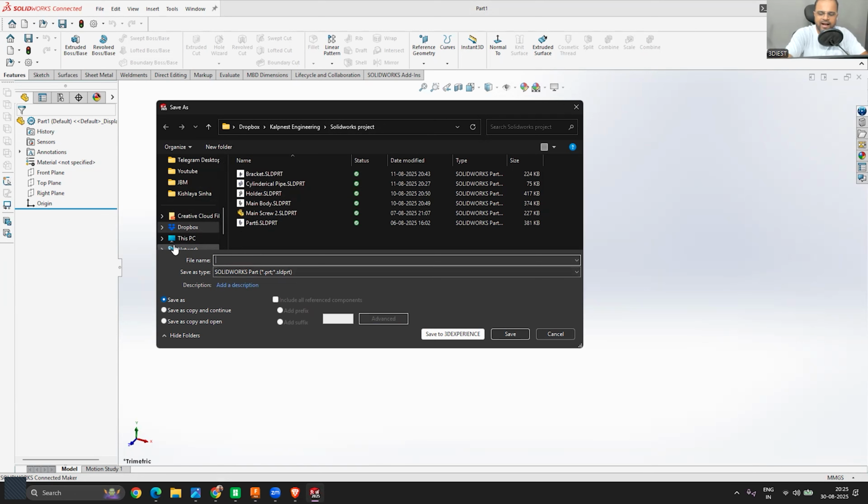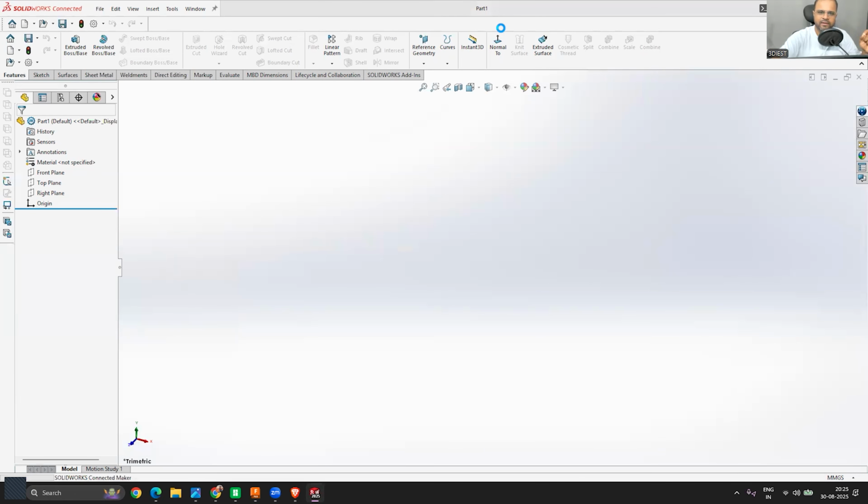Let's say I will write day 1, right? So I have given this file the name day 1. And if I click on save, you can see the name on the top just got updated to day1.sldprt. So what we did, we have saved this file, right? Now, once we have saved this file, the next task is important. Now, this was the one way to save the file.